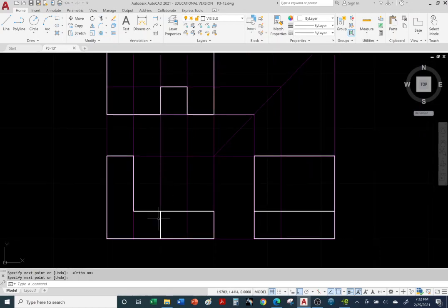See, that's the reason for these construction lines, is to help you line up your new geometry with existing geometry, right? All right, so I need this corner to create this object line, right? It represents this opening here. All right, so let's go to line command.